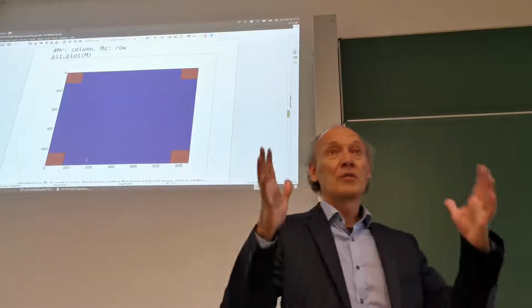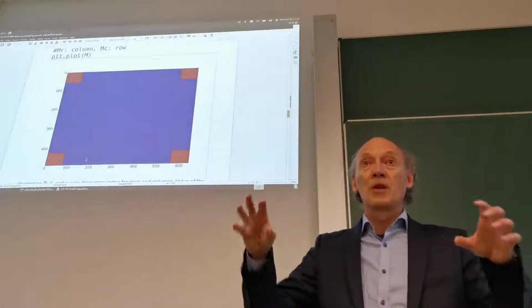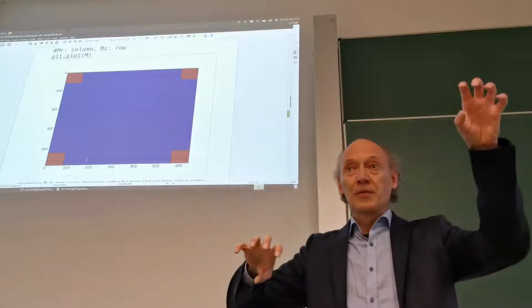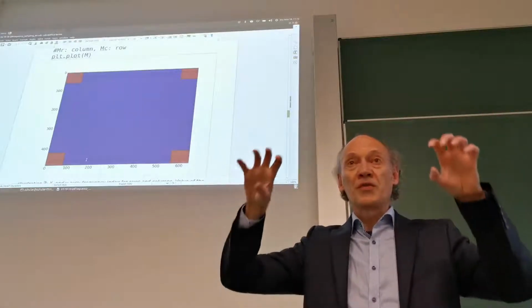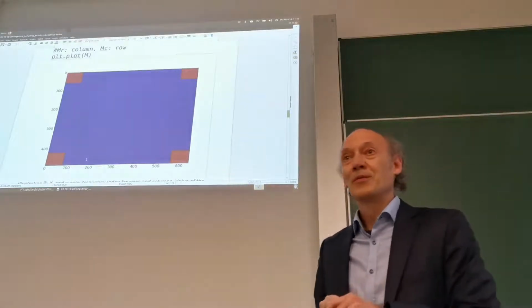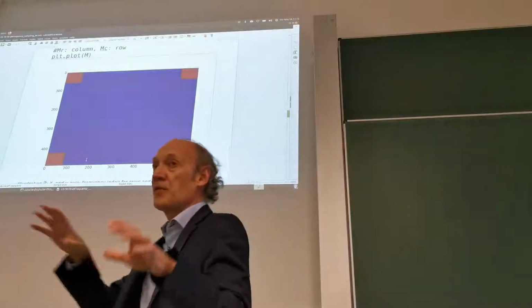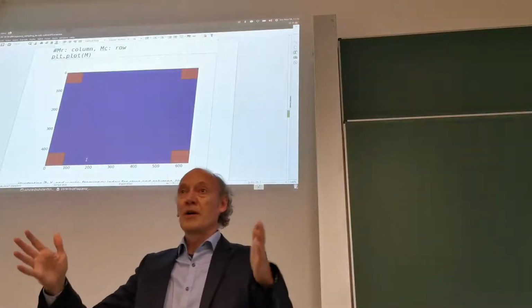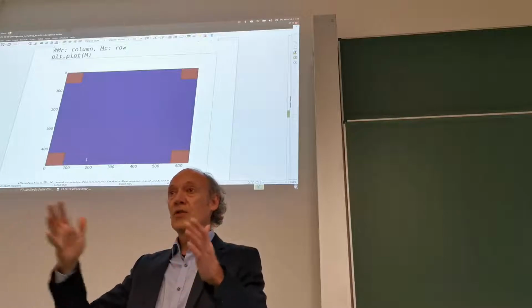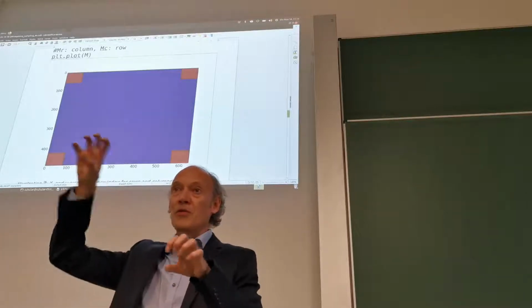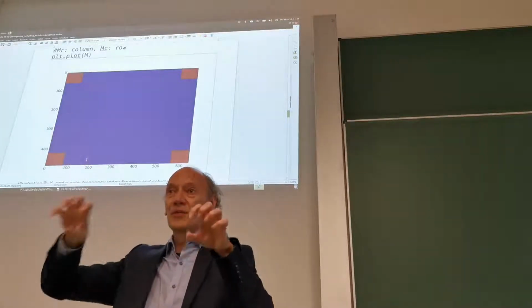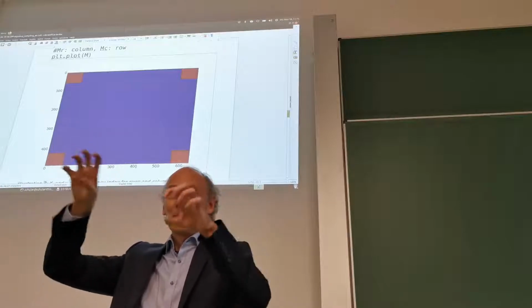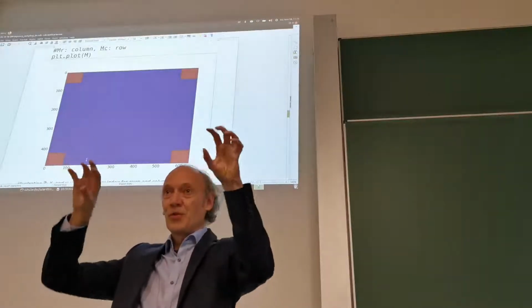So we have a 2-dimensional mask, where we have the corners with 1s, and remember the corners have the lowest frequencies. Maybe you remember last time's demo where we applied a 2D DFT to a live video, and there we saw in the corners the bright regions, right? Bright little stars in the corners.